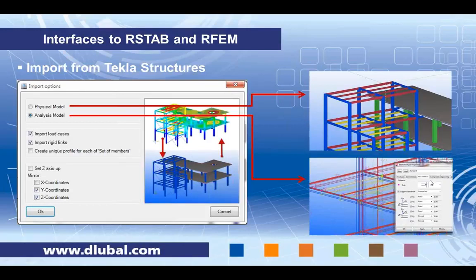And inside Tekla, we have access to information like how is a beam connected to a column? Is it a moment connection, or is it a pinned connection? And I can set the degrees of freedom. Typically, this information in an architectural software is of no relevance.